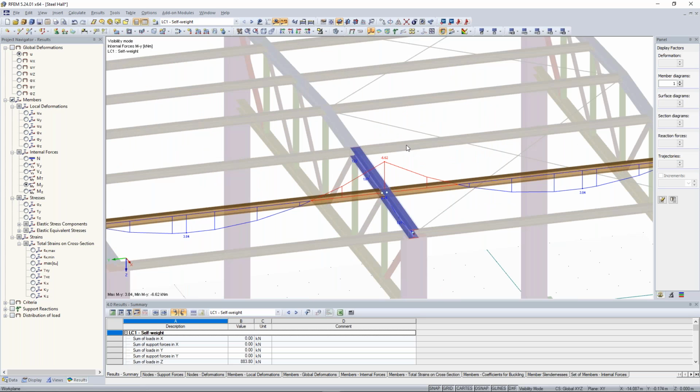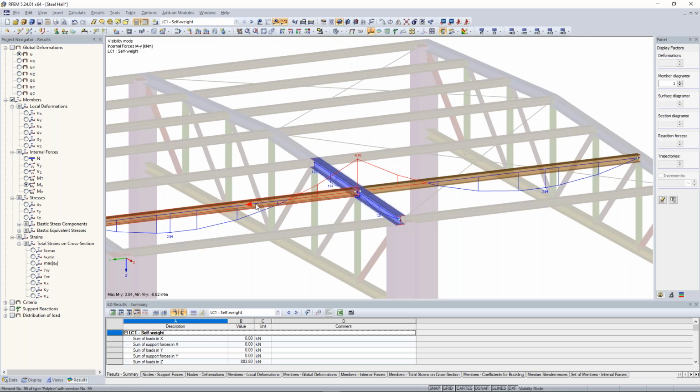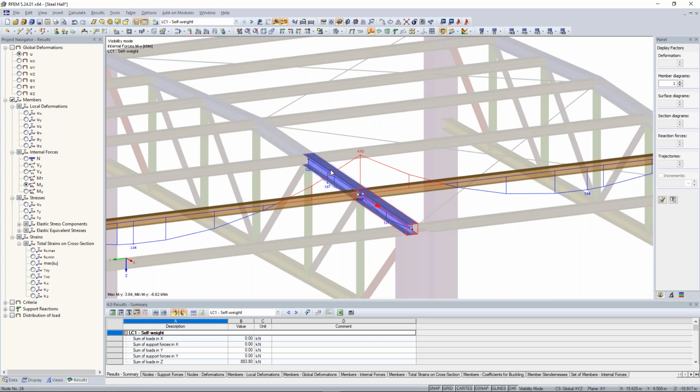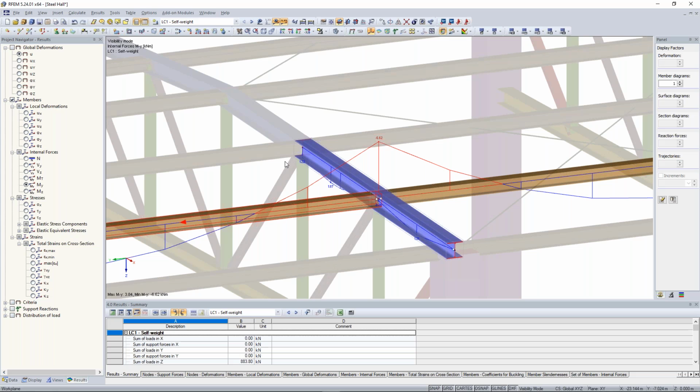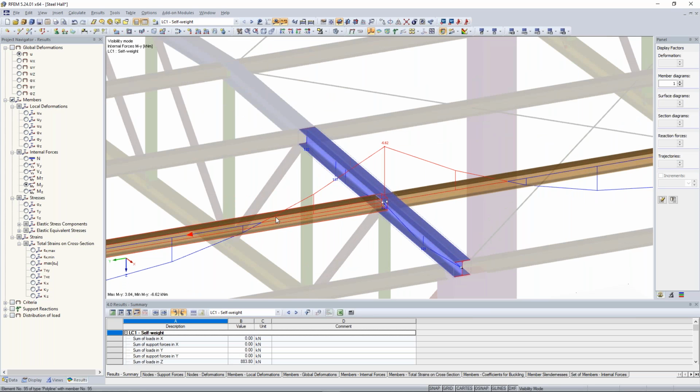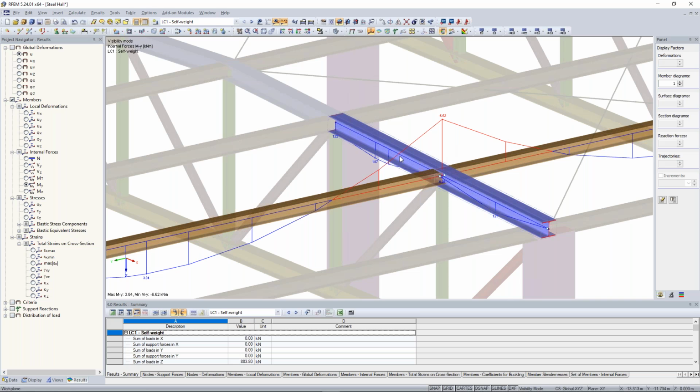So as you can see here we have our continuous beam, and here we have also a beam. And what I have done with the scissor hinge, I said, okay, please create me a scissor hinge that I transfer only my shear forces, so my vertical forces, to that beam in this direction, to the blue beam. And everything else, this should be considered in that continuous beam. And you can see no moment was transferred to the other beam.